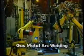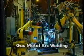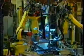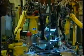Gas metal arc welding uses a continuous solid wire electrode for the filler metal and a shielding gas to provide the desired arc characteristics and protect the molten weld metal from air. Gas metal arc welding is suitable for welding many types of joints of most any metal in all welding positions.